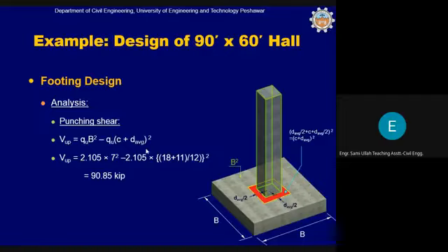For practical reasons, if you construct a column and extend its reinforcement into the foundation and apply a load on the column, the load will basically make a hole in the pad, but this hole will be made at these yellow boundaries, not at the perimeter of the column.